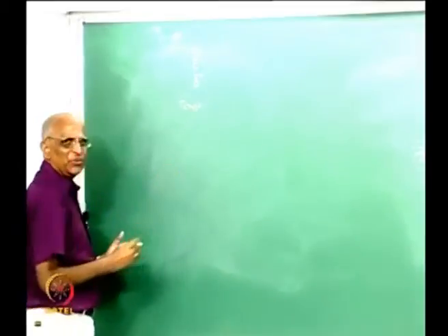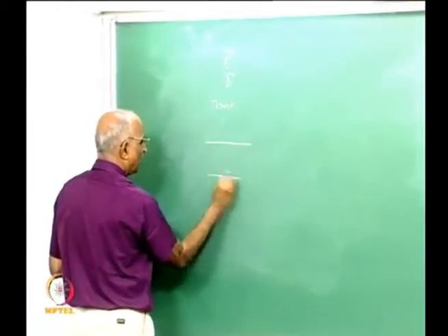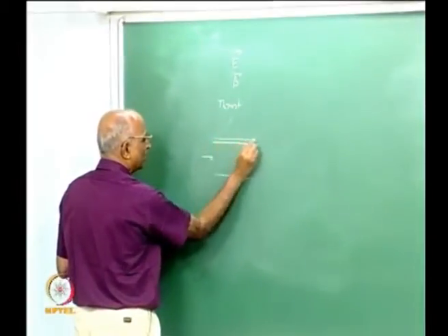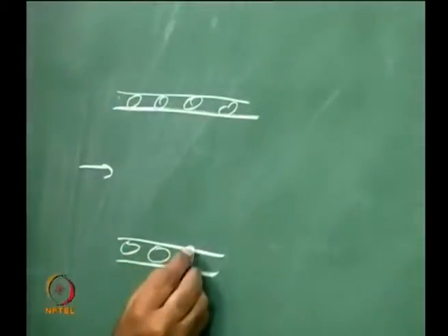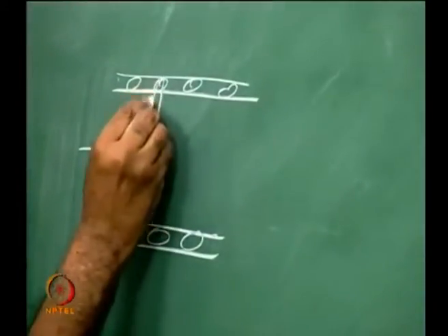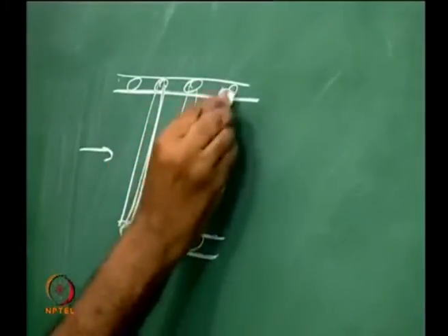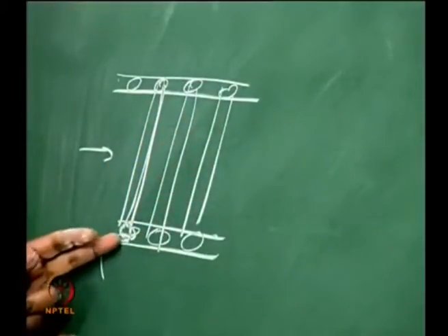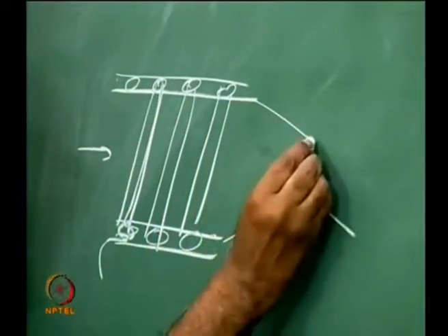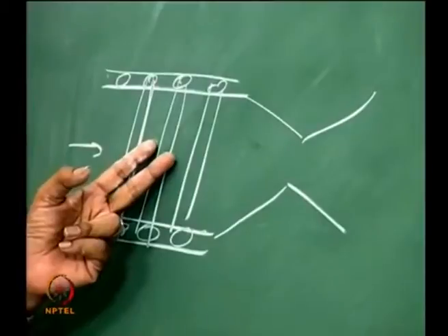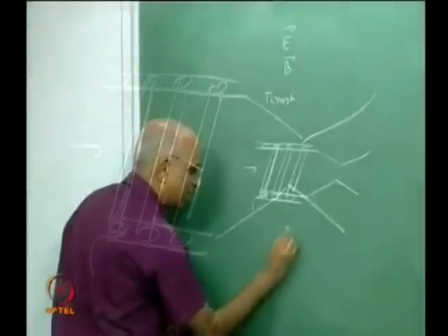But something very apparent which we did not do was this: supposing I have a gas flow and I use a series of resistances, a resistance coil on the wall, and I pass current through this. Well, I can always heat this chamber, and I could have a regular nozzle. That means I heat the gas using a resistance wire, and these are known as resistojets.